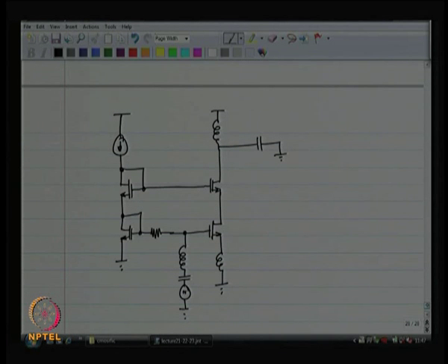This is also wasteful in terms of current. If you plan to have I bias flowing over here and you put a 1:1 current mirror, then you are consuming 2x the current, right. So, probably you want a fraction of I bias, let us say I bias by 100, and you make these W by L's in the ratio of 1:100. So, this also could be done.